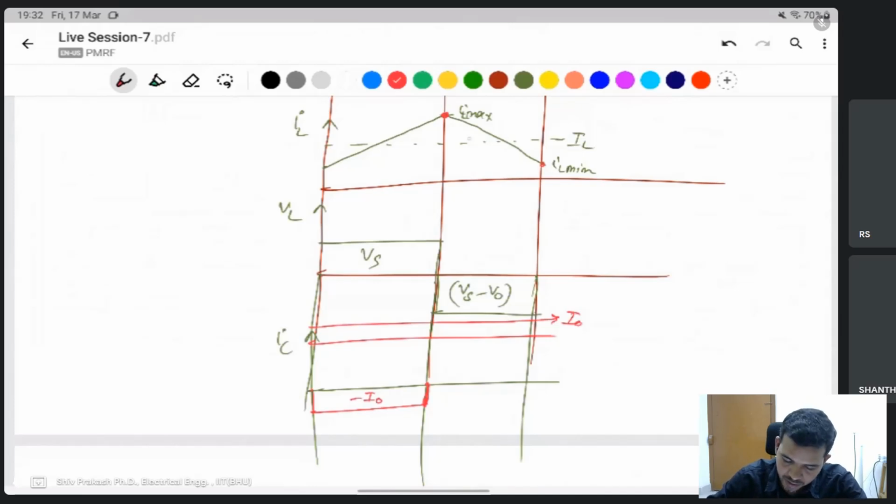So minus this one, IL minus of I naught. Then you could say that the capacitor current goes like that, this IL minus I naught is 0 or not 0 depending on the ripple of the inductor current.